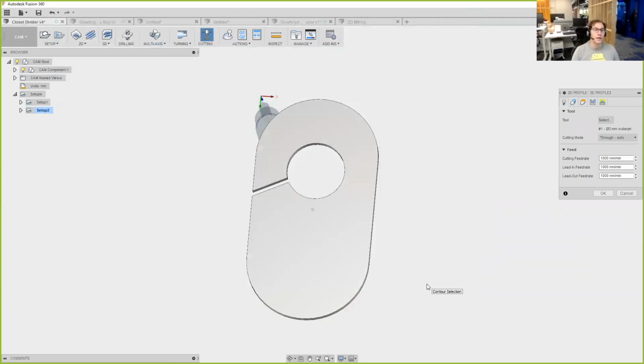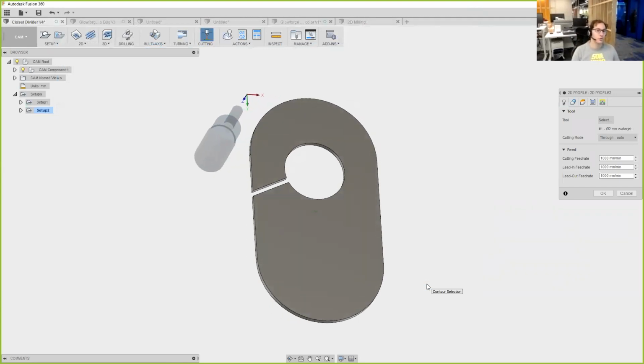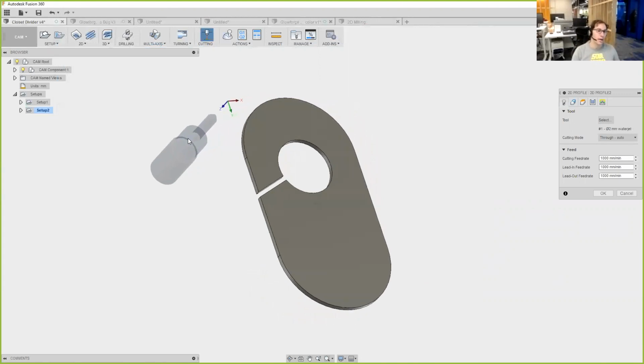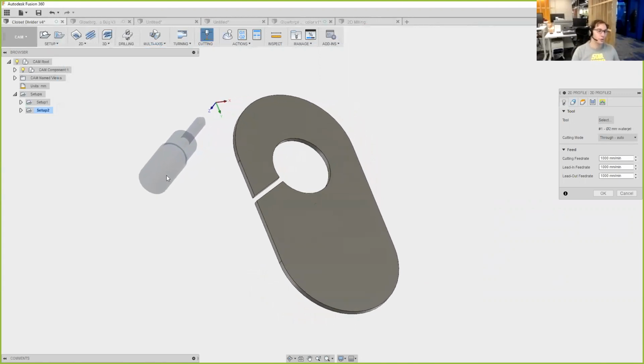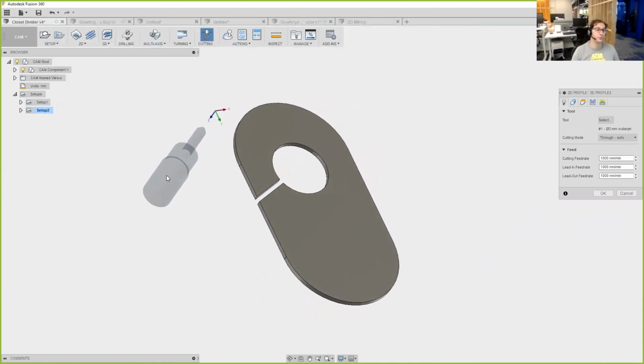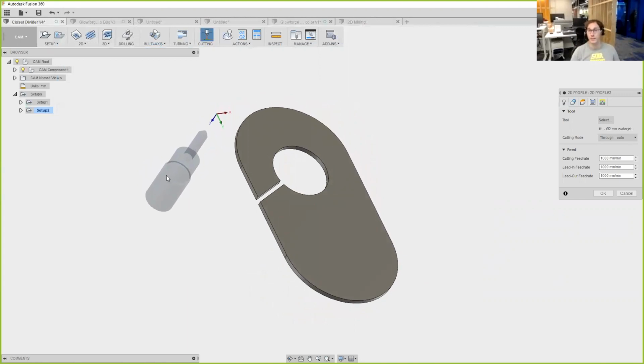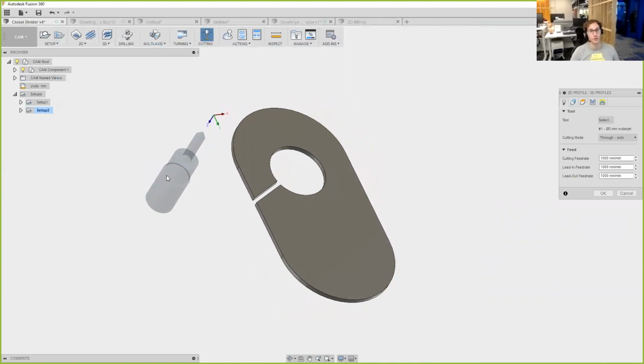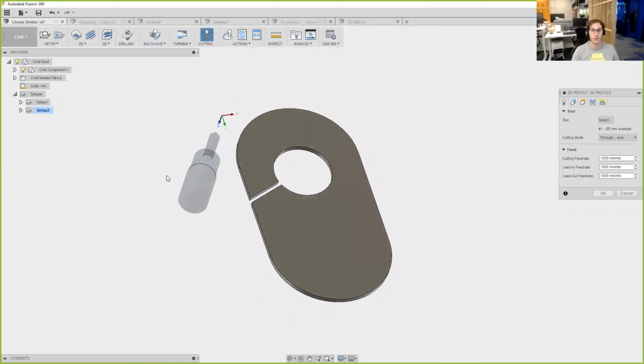And there we go. Now, even though I selected my coordinate system correctly, I am going to note that the laser cutter, for whatever reason, thinks that the laser head is from below. And I don't love that it doesn't visualize the way I'd like it to visualize, but I'll tell you right now, if this is what you see on your screen, this is going to be correct for your Glowforge. This might not be true for a water jet cutter or a laser made by someone else, but for your Glowforge, this is going to be how you preview it. And so we're going to continue.